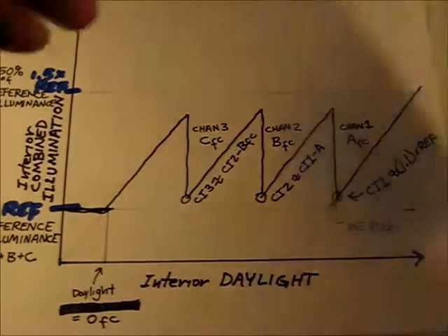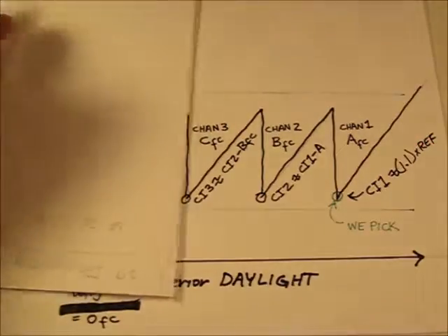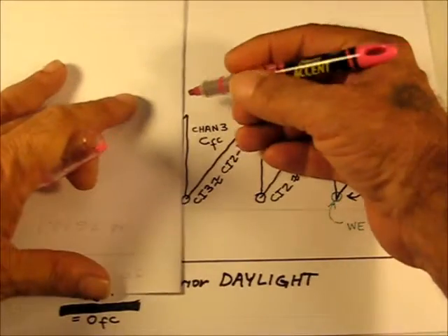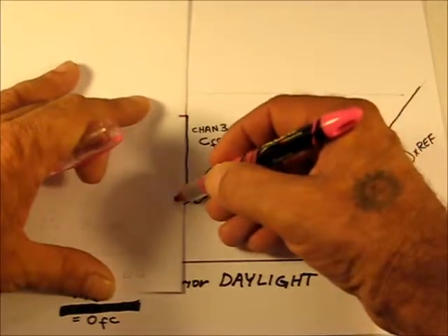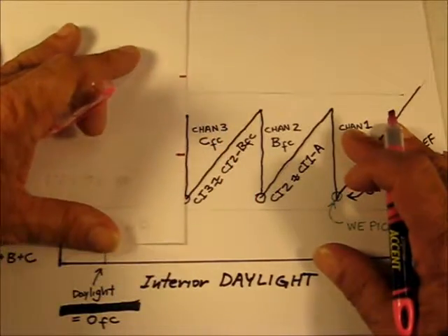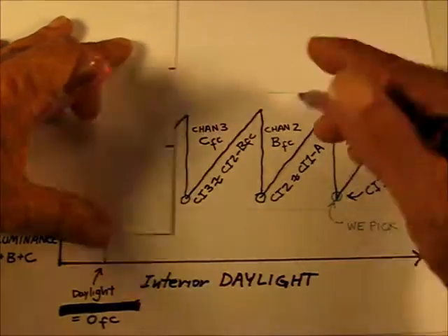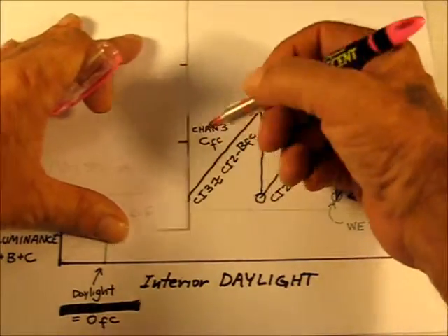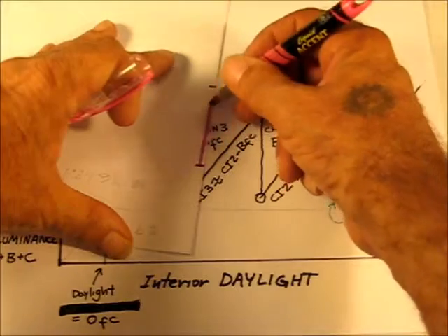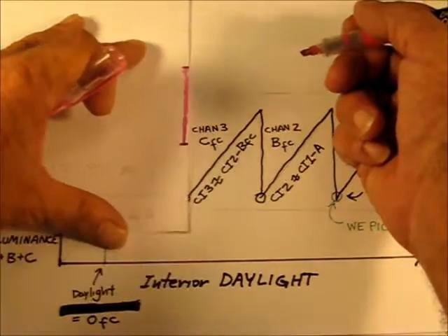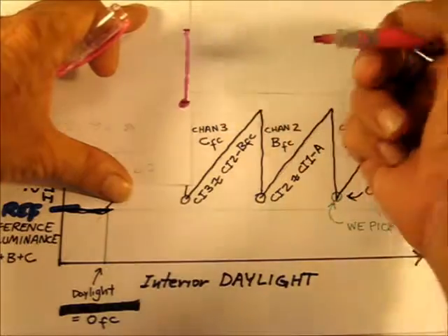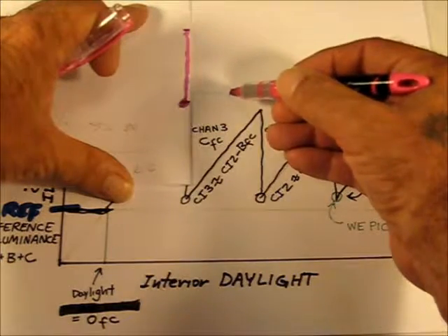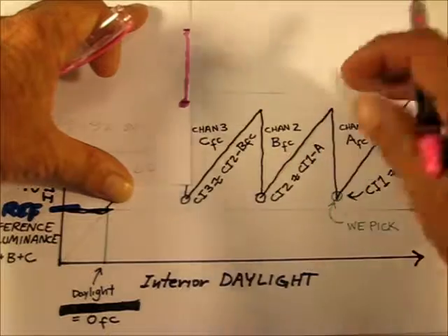This is very important because we are going to need to ensure that when we insert our deadband and this stage of light switches back off, this switch off level right here needs to fall between 150% of reference and our reference.